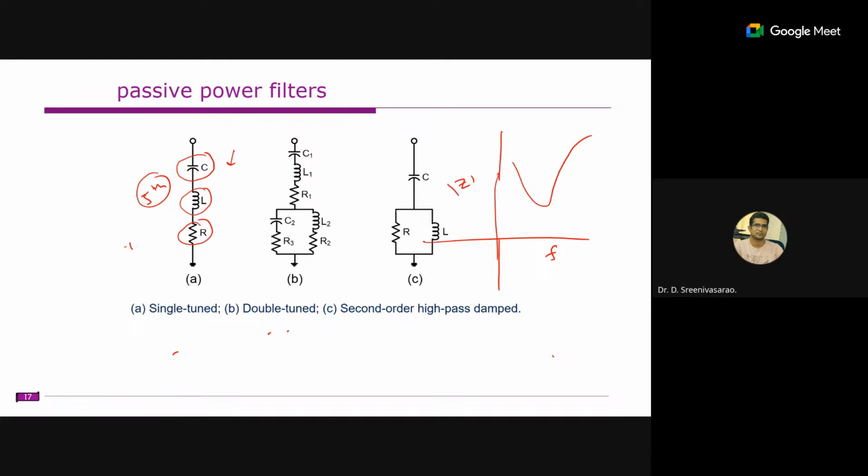So due to aging, this middle point will deviate at some point, and you will get a new frequency. That is one of the drawbacks. Therefore, when installing this power filter, instead of tuning perfectly at the fifth order harmonic, they will normally tune at the 4.7th order harmonic or something like that.